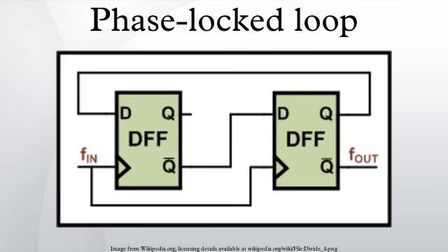Bringing the output signal back toward the input signal for comparison is called a feedback loop, since the output is fed back toward the input, forming a loop. Keeping the input and output phase in lockstep also implies keeping the input and output frequencies the same. Consequently, in addition to synchronizing signals, a phase-locked loop can track an input frequency, or it can generate a frequency that is a multiple of the input frequency. These properties are used for computer clock synchronization, demodulation, and frequency synthesis, respectively.